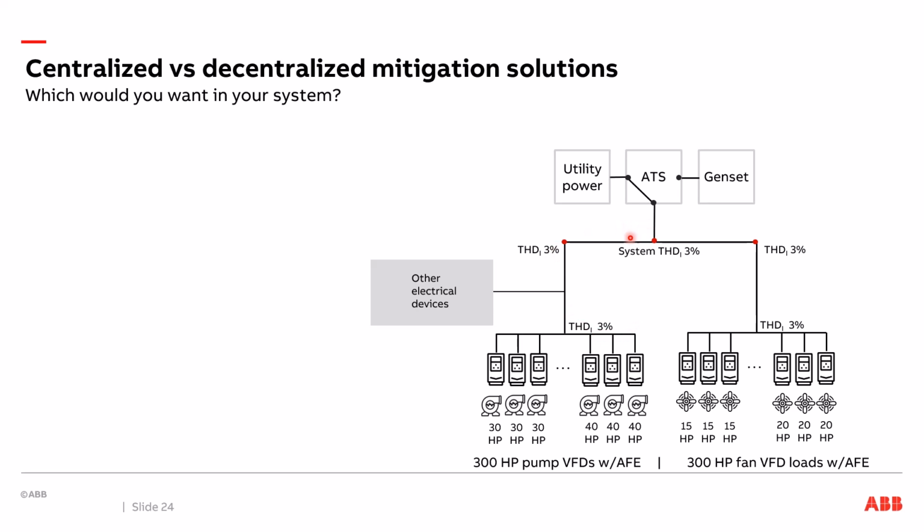I'm never going to have to worry about single points of failure or adding multiple layers of harmonic mitigation all over because my drives aren't creating harmonics in the first place. And that's one of the biggest advantages of that decentralized solution.